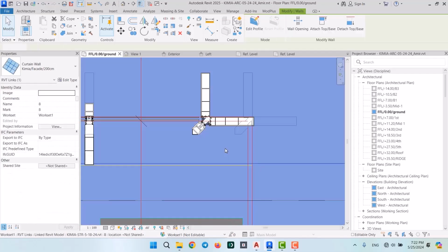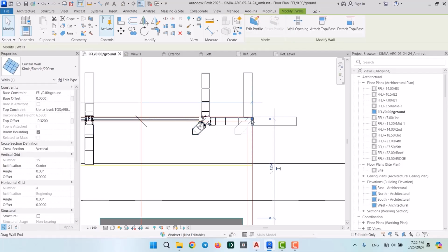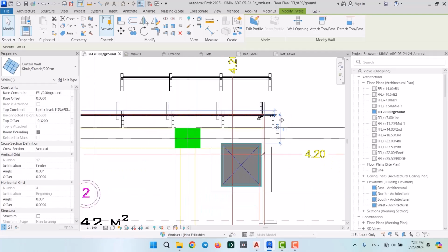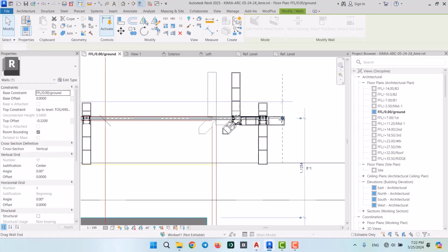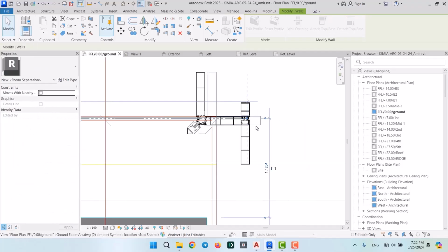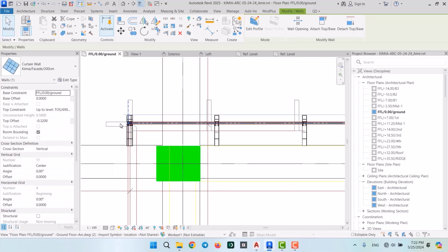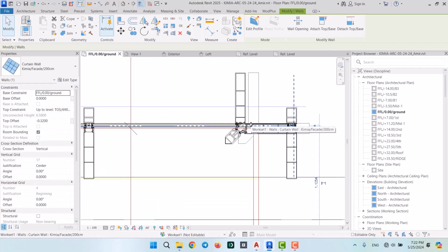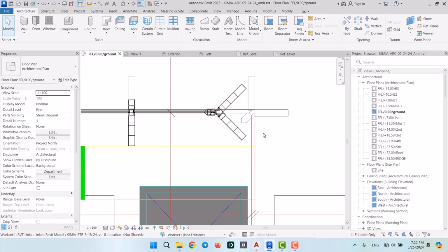And there we go. Now there's something going on here, which is that this mullion is not in the right place, and it's not like you could, for example, drag it to reposition it. And the reason is if you try to do that, then that'll mess up something else. For example, do you see how far the curtain wall needs to go? It needs to be up to here. So if we try to drag one mullion to reposition it, then that'll mess up the other mullions. So that's a complicated path to take, and it might just make things worse.